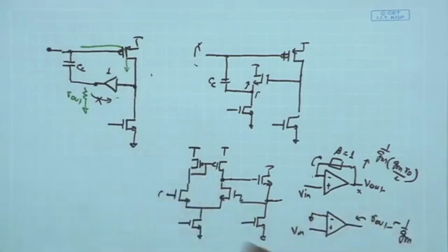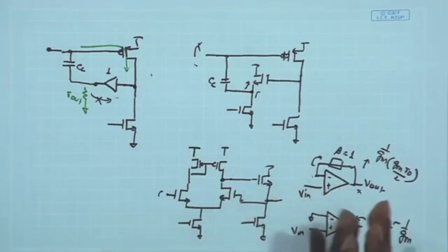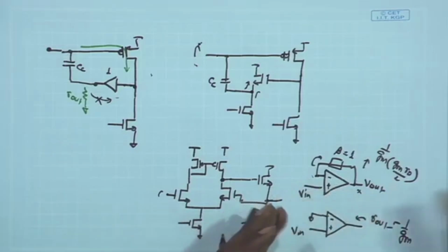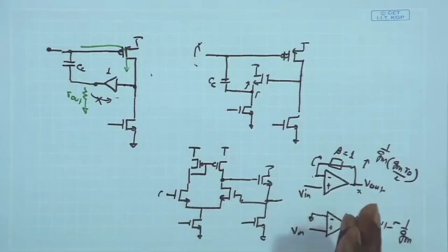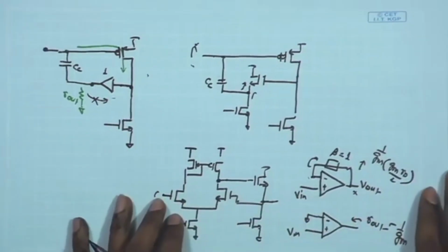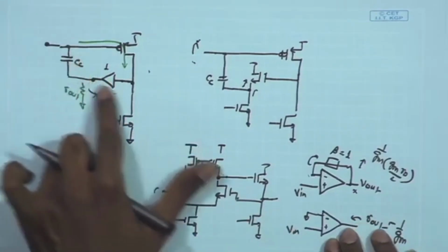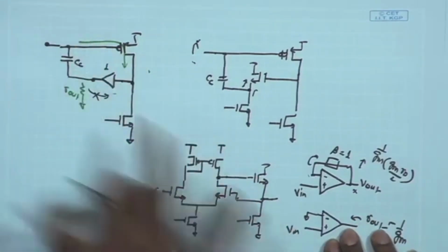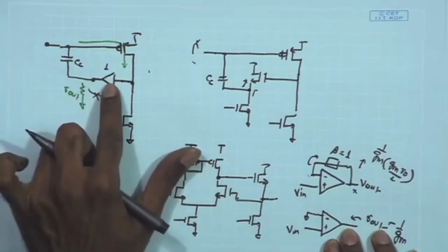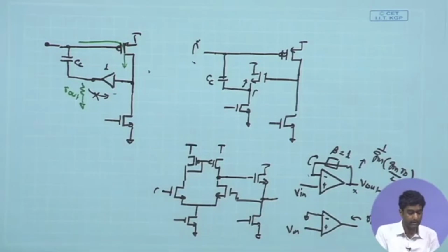For the common mode feedback, we discussed a condition where we are only looking for the DC biasing part. Therefore, even if we make the common mode feedback circuit very slow, if we make the error amplifier of the common mode feedback very low bandwidth, it does not hurt the overall differential response. But here, since this is a part of the differential operation, we need this buffer amplifier also to have sufficient bandwidth close to the main amplifier.